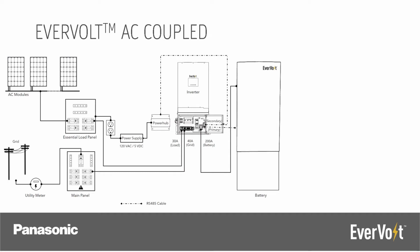This is a detailed look at a typical Evervolt AC coupled wiring diagram. You can see that on the Evervolt inverter there are a few major connections. You have your battery connection that goes directly to your battery cabinet. You have your grid connection, and that's going to go to a 40 amp breaker on your main service panel. And then you have your load connection, which is going to be tied into the essential loads panel that the customer chooses which circuits from their house they are going to back up.